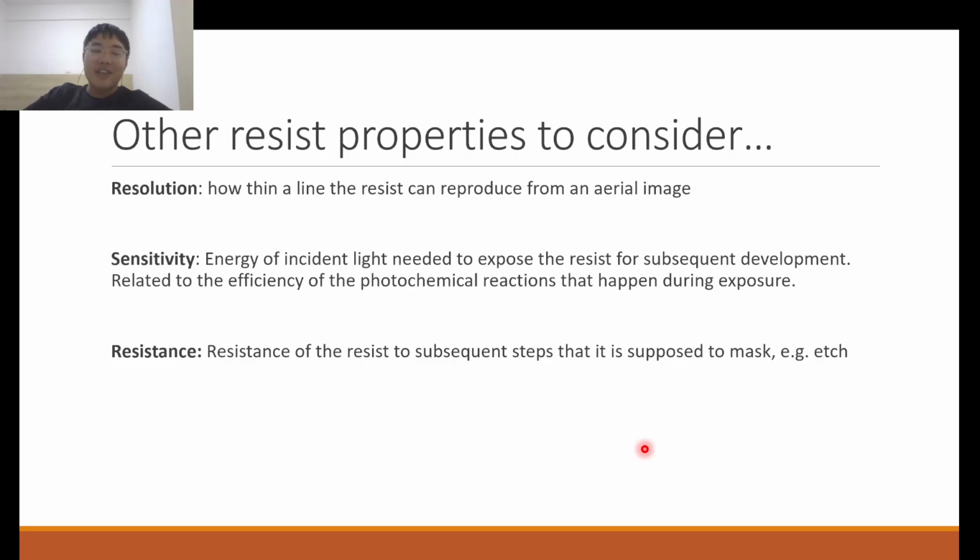And so this is related to the efficiency of the photochemical reactions that happen during exposure. The more efficient the photochemical reactions, the less dose of light we need to illuminate the resist to achieve the good development outcome. And lastly is the resistance of the resist to subsequent steps that it is supposed to mask.